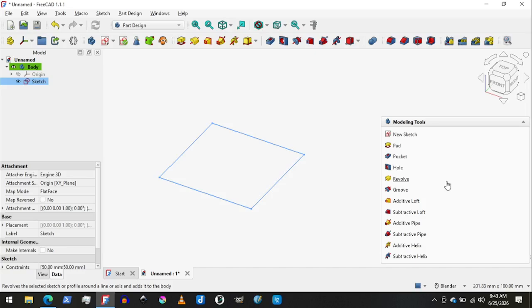Now here I could kind of cheat because the circle is centered. If I go back to the drawing, the circle is centered on the face. Okay. I could just cheat and center it here on the origin, set it to 25, and call it a day. Okay. So I hit those. Now I have the circle, a two-dimensional circle.